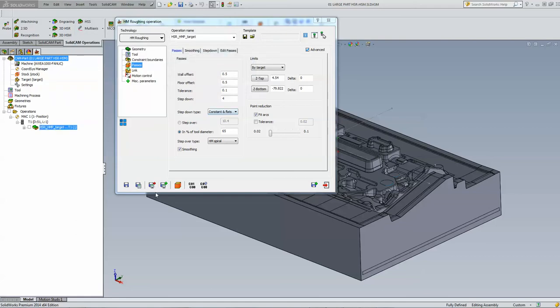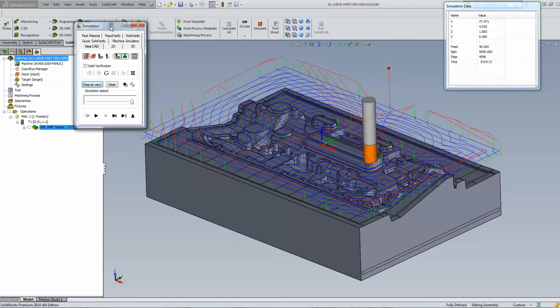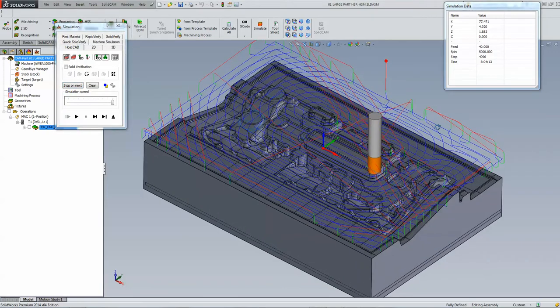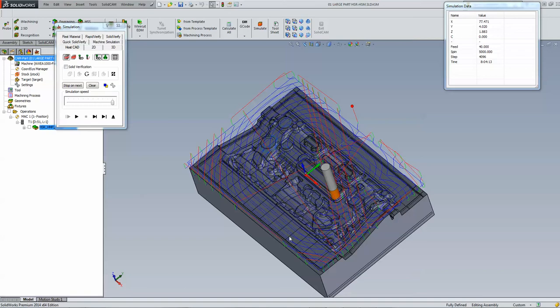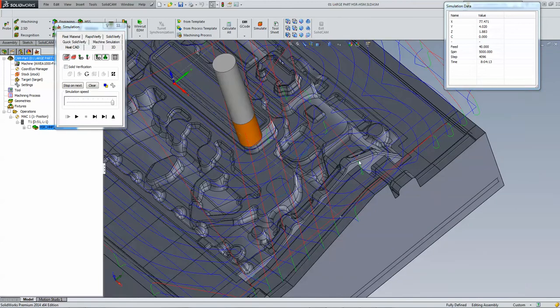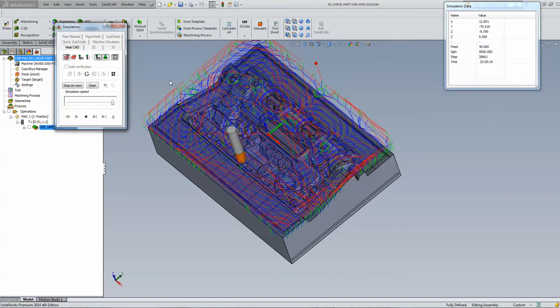If we take a look at the toolpaths that we have over here, and I'll start running it in my regular mode over here. Let me just stop it for a moment, and you can see right away that it's actually working really nicely. It's coming from the outside, clearing off the corners, and then as it goes to the middle, it'll start doing more of a spiral around the part itself, as shown over there. Also going around any kind of island that it may have, such as in the area over here. So it'll do that for the entire part and give you that nice toolpath that you need. Actually a very efficient toolpath going down in the part itself.